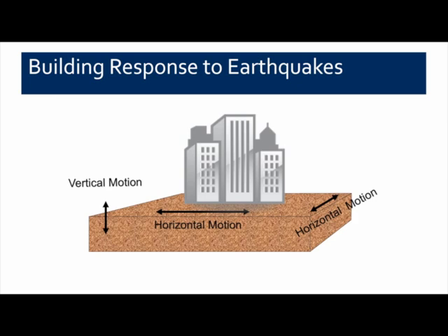So when we're talking about earthquake forces, we need to consider both horizontal motions and vertical motions that might be imposed on the building during an earthquake. Now, for structural design purposes, we consider that the horizontal motions are the most significant in terms of design, and there's two reasons for that.